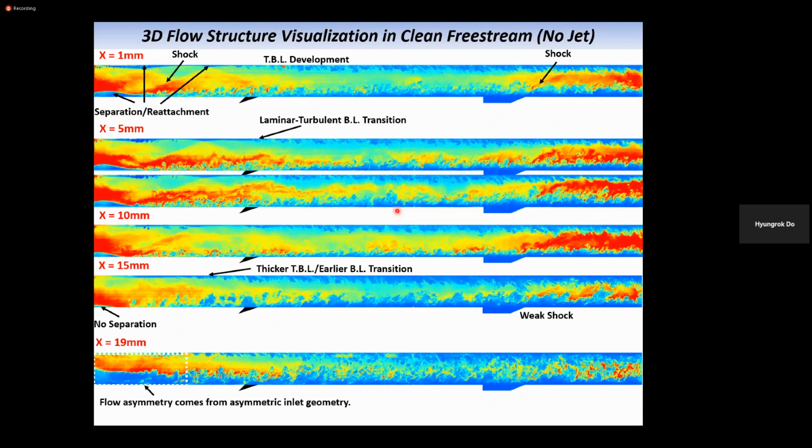So if you see each slice, at 1 millimeter away from the center, you see a clear structure of the sharp waves, and near the sidewall structures, you see just a turbulent and random flow structure, because the flow transition from laminar to turbulent has been occurring at that location. Okay?